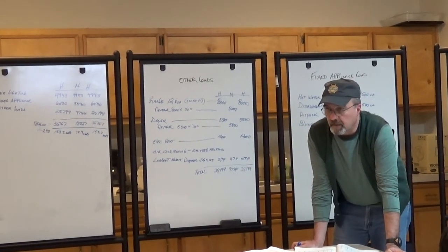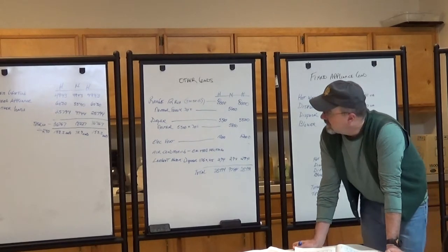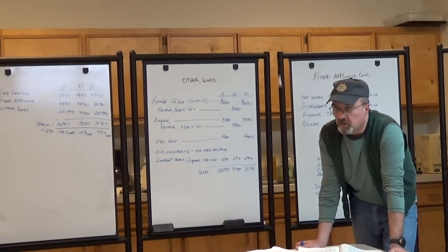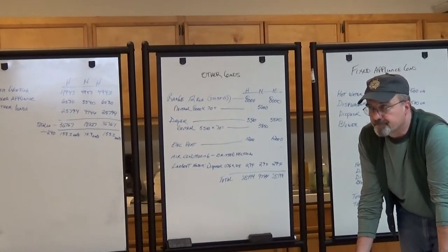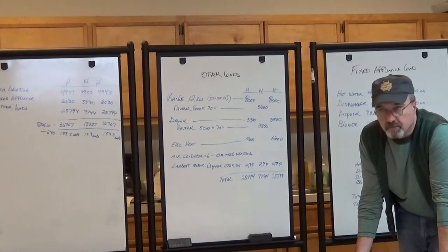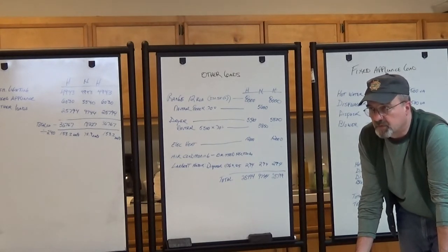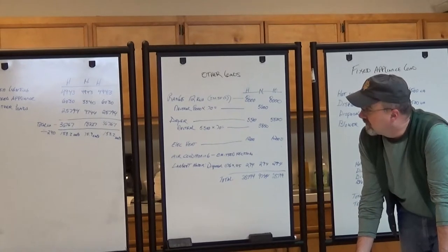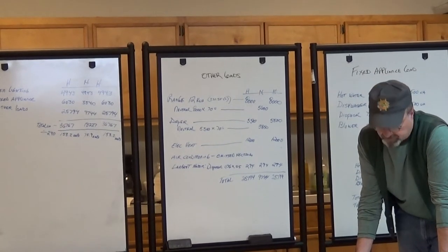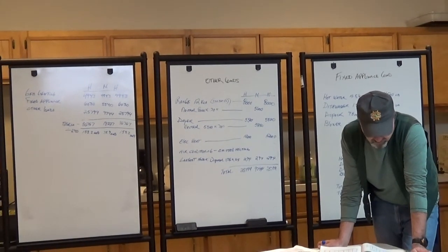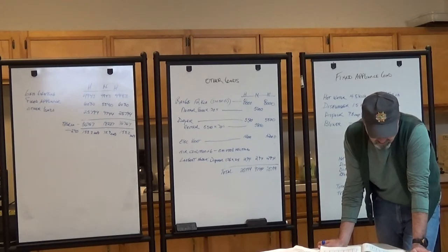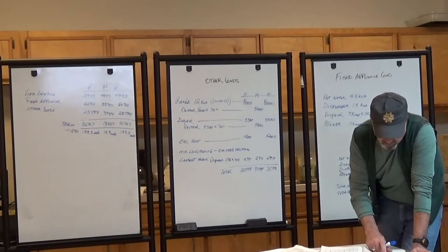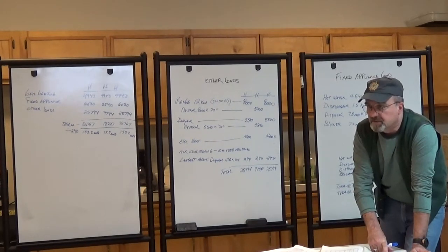Okay? All right. So for our hots, what size wire are we going to need? 90-degree wire. We want to use 90-degree copper wire. What size wire are we going to need for 153.2 amps? 1-aught. Mm-hmm. 1-aught wire. That's good for 170, right?